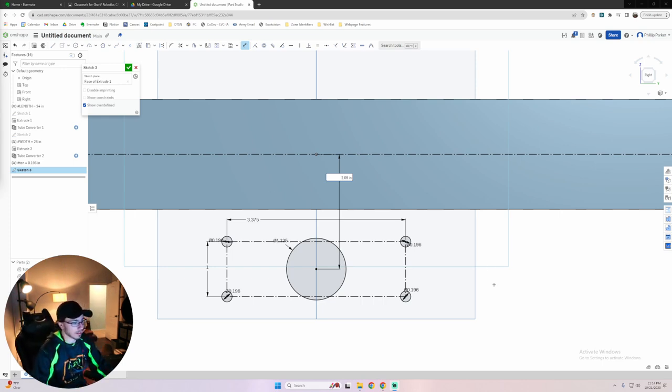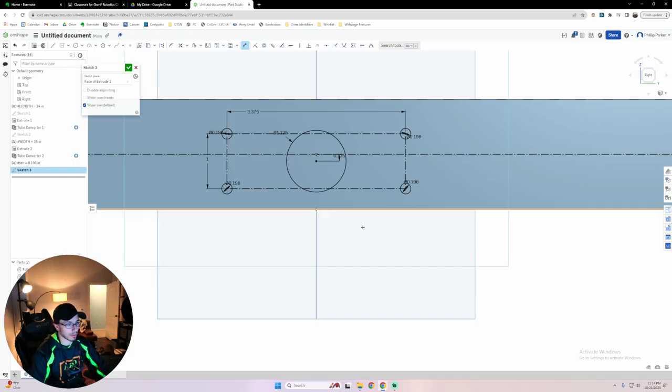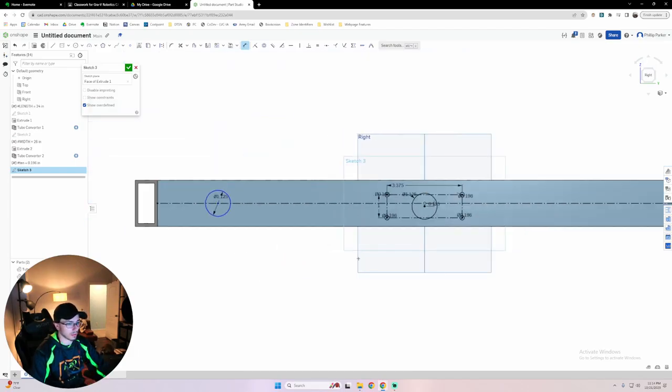Okay, so I can dimension it. And let's say I dimension it to... I'm going to dimension the drop center is what I'm dimensioning. So I'm going to dimension 0.125, which is 1/8 of an inch drop. Now what I can do...